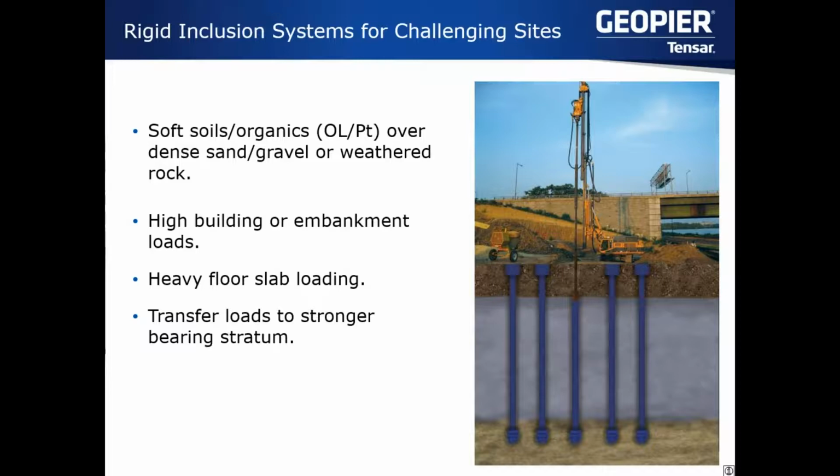Because of that, it's an element which relies very heavily on confinement. And if we're in soft clays or organics, particularly in organics, over time we're at risk of degradation of that surrounding soil, and as a result, stiffness of the element is going to degrade over time, and an aggregate pier isn't really going to be able to provide that load carrying capacity for the long term. And that's not always the case if loads are very light.